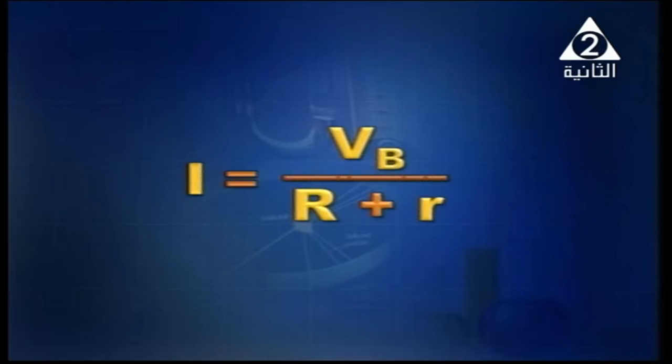And what about the relation that expresses Ohm's law of closed circuit? Of course, current through the battery, the main current, equals V battery over R capital plus R small. R capital plus R small means the total resistance of the circuit, external resistances as well as the internal resistance of the battery.